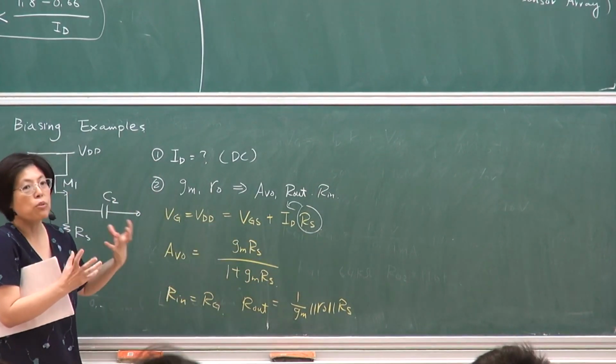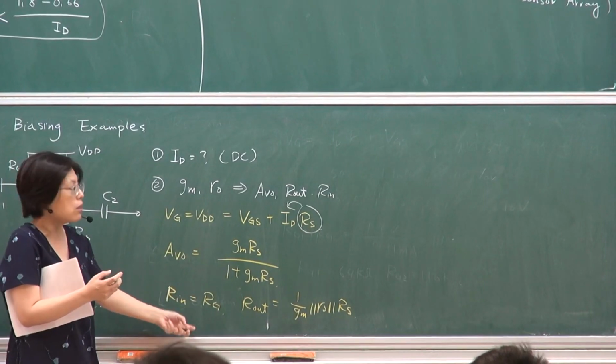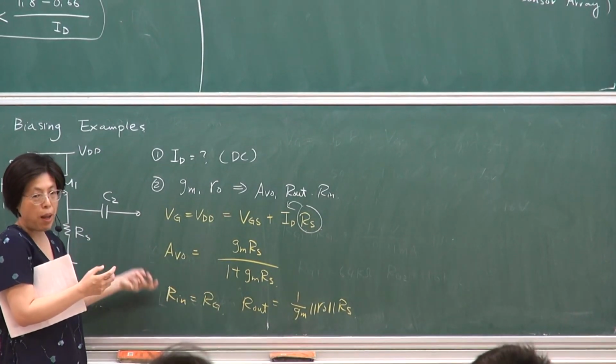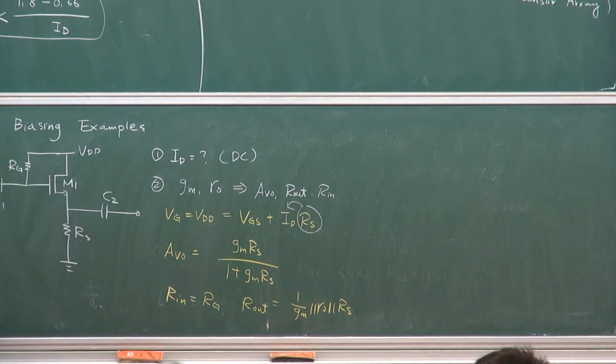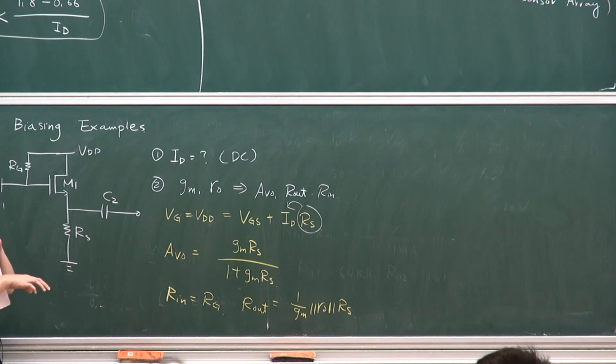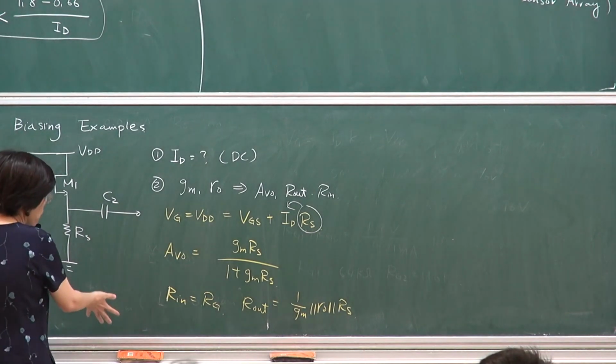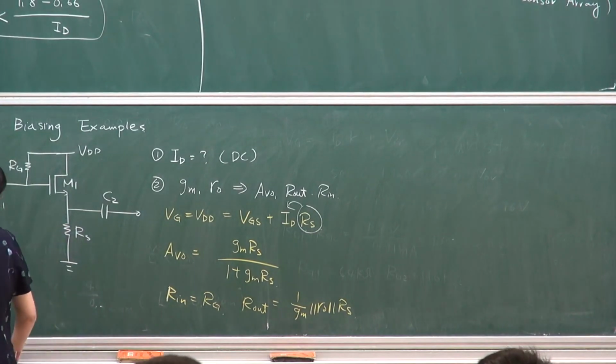Then there's no freedom in determining your output resistance, since the small signal parameters are fixed once the biasing point is fixed. So it allows you very little freedom to independently determine the best place to stand, because the performance when you stand there is linked together. So it's very rare you can get the optimum point.